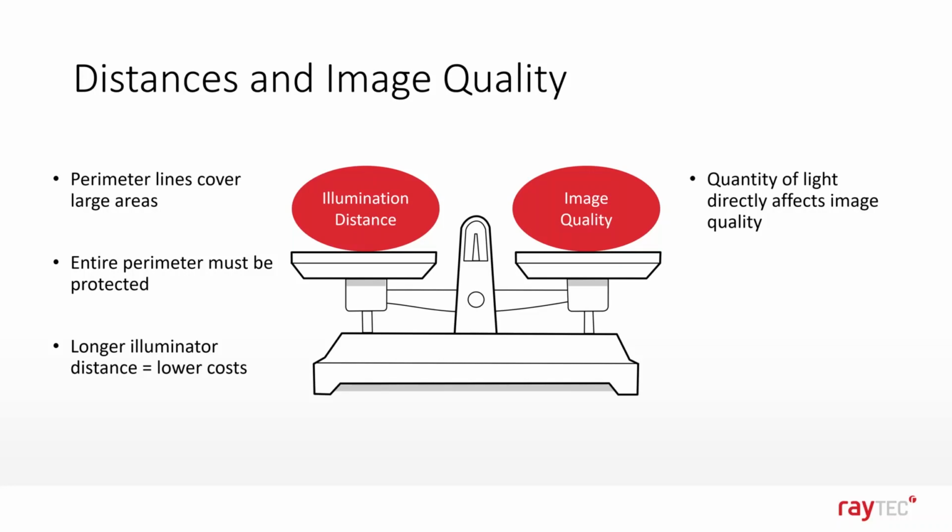So let's say, for example, we are using this mentioned 500-meter illuminator. Somebody comes on scene at say 30 meters, they're going to be likely overexposed. But if somebody comes on scene at 500 meters, the exposure is going to be a lot less on that as well. So these factors do need to be considered, especially if you want to guarantee a uniform light level. So yes, we can go very far, but sometimes it's optimal to use a little bit less to get a more uniform light, depending on the requirements.